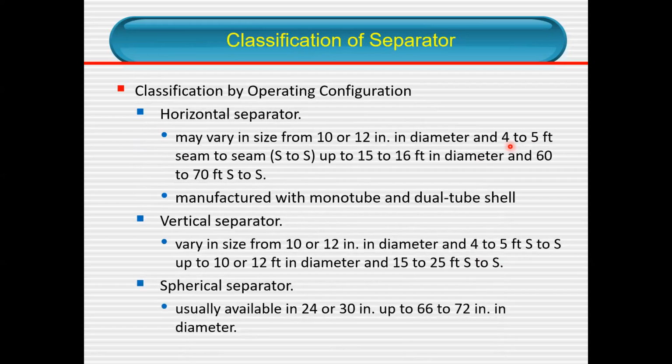Okay. What are the types of separator? Horizontal separator, vertical separator, spherical separator, coming in different diameters. An economical evaluation will be done to decide which is the right separator. Also on a technical basis, if you have a lot of gas, of course you need a vertical separator, better than a horizontal separator. Why do you need a spherical separator? They all have their purpose. Which one needs to be designed or bought depends on each particular field.